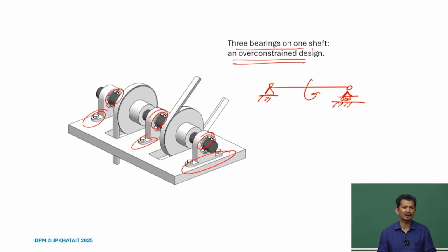So, definitely it is not advisable, because any error, any crookedness in the shaft, any offset in the middle one, suppose if it is supported on the last 2 bearings. So, it may be okay when we assemble it, but as it starts rotating, any offset will put a lot of constraint on the shaft, on the frame, and will cause a lot of issues with the design.